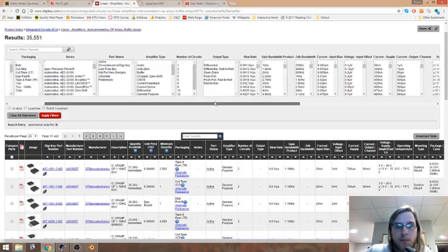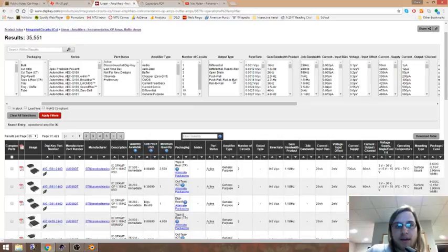Another good thing to consider that I always like to pick out is op-amps that are rail to rail. What that means is, the cheaper op-amp circuits, if you supply them with 5 volts on the supply line and you want to amplify a signal, you will only be able to get up to about 4 volts, and at least 1 volt is wasted in the process of doing the amplification. But rail to rail allows you to use the full potential of your supply.